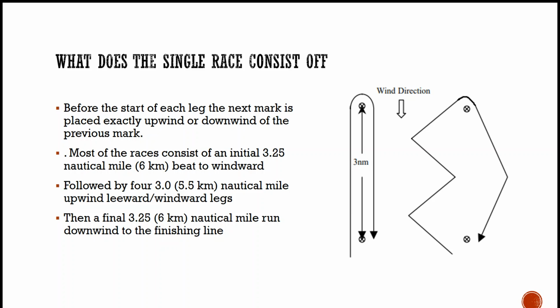Now it's aerodynamically impossible to get a yacht to head straight into the wind, and so tacking is essential on the upwind leg. However, while it's possible to get a yacht to head straight downwind, it's generally better for the yacht to head off at an angle. This situation is illustrated schematically in the figure to the right, where on the downwind leg, the angles sailed are smaller than that on the upwind leg, but these small angles are very significant.